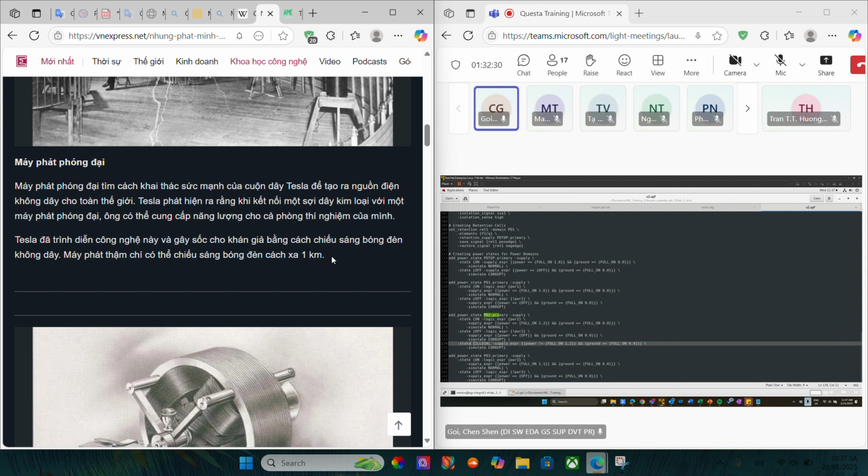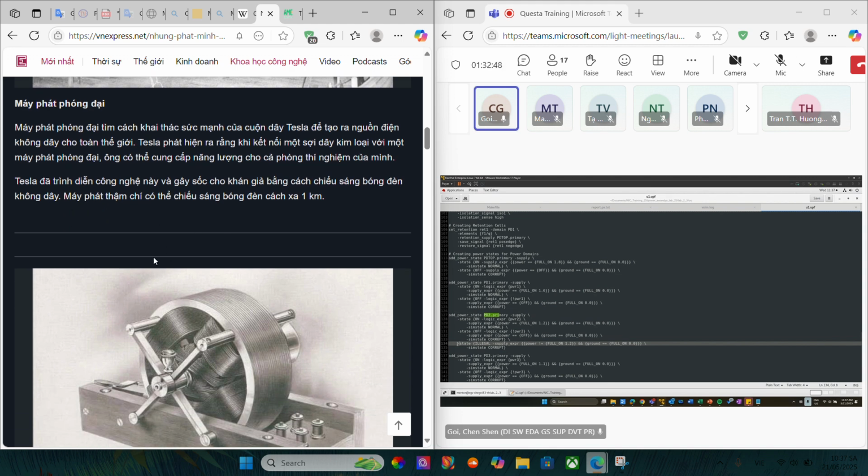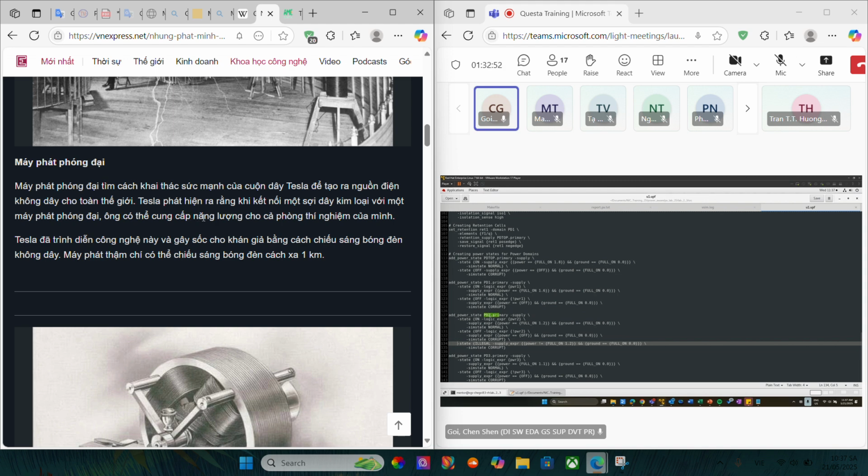However, there's also an illegal state that we mentioned here. The illegal state is when power is not equal to 1.2 and the ground is full on. So we know this state table for the PD2 primary supply set. Now we have to check why it is giving us this illegal state. Then we'll have to check what kind of supply we gave to this PD2.primary.